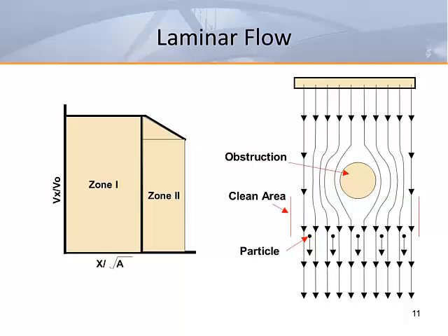The 35 foot per minute air velocity is important because the differential temperature between the patient's body and the room generates natural convection currents from the body at about 35 feet per minute. These natural convection currents create a defense system for the patient during surgery. A higher velocity airstream will increase the chances of contaminants being driven into an open wound.